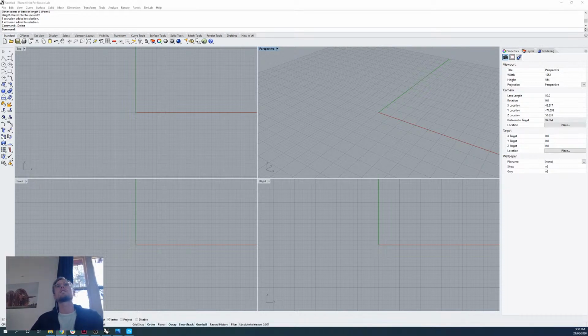The other thing you want to do is organize all of your layers based on your presentation needs. So don't have your layers as option 1, final, option 2, final, option 20, and all these different things going on that you can't easily navigate inside of the Fologram app. And the other thing I'd highly recommend is to create a separate Rhino file for your AR presentation. Your AR presentation is obviously its own thing. You're trying to show something through that application, so try and keep it separate from your design model when you're going into Rhino.